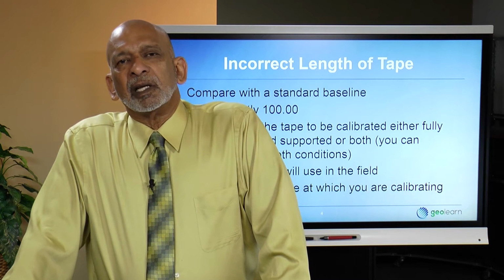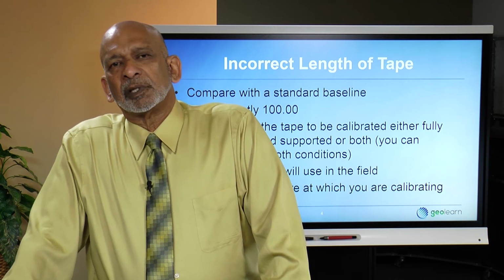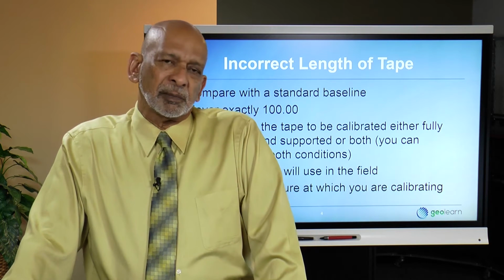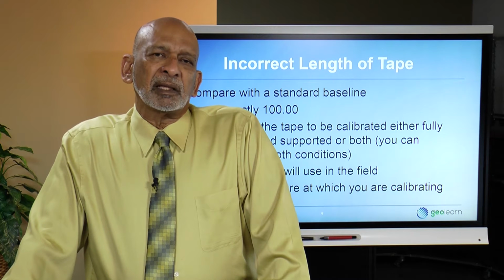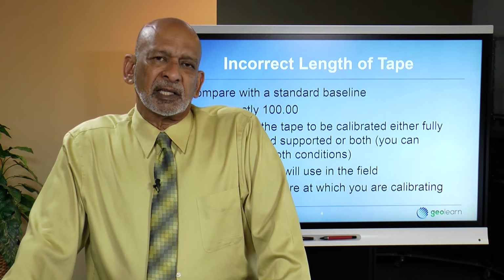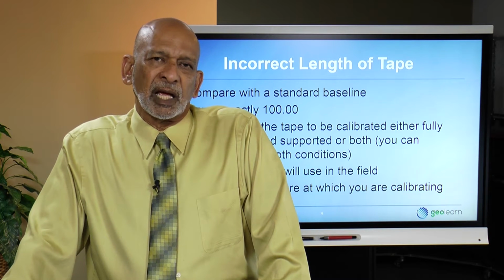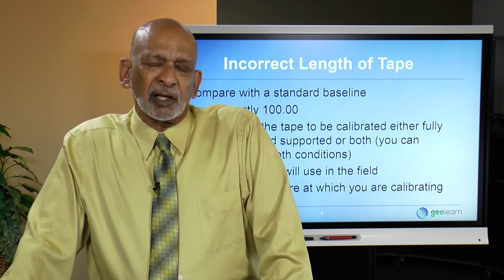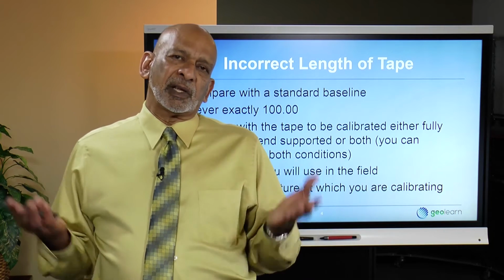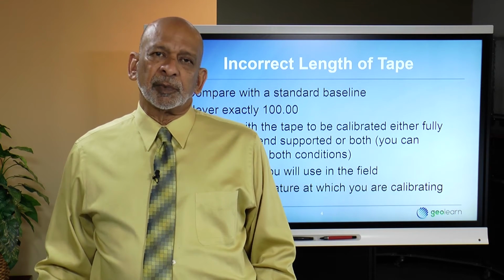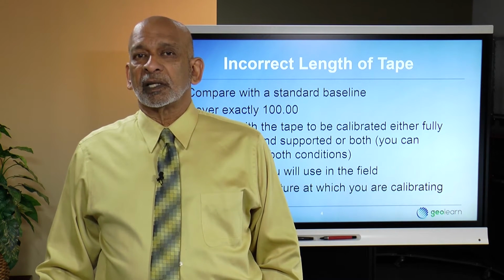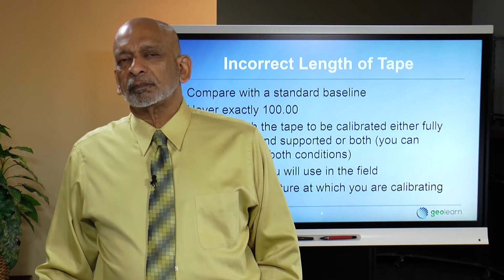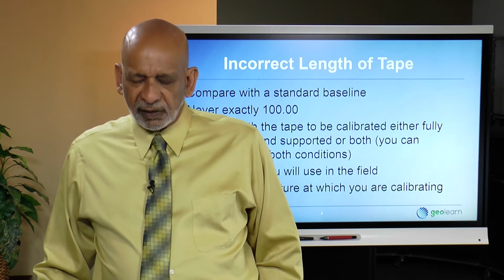built in a factory, so chances are temperatures are around room temperature, whatever that might be. So keep in mind that as steel heats up, it expands. As steel cools down, it contracts. So there is an impact. And so you can actually have, with variations in the room where the tape is being made, if they don't control it strictly, the tapes actually come out with different lengths.